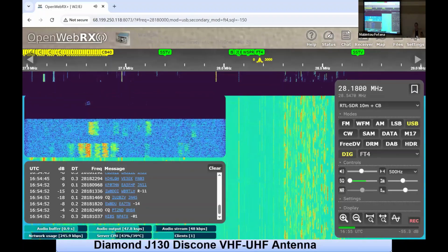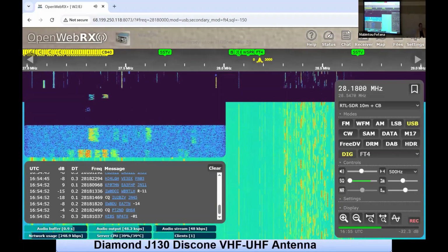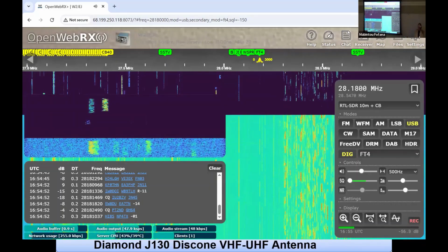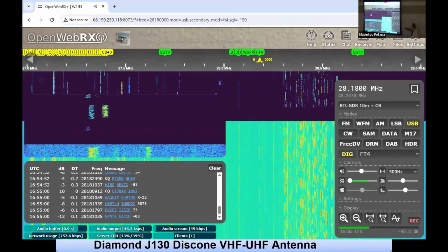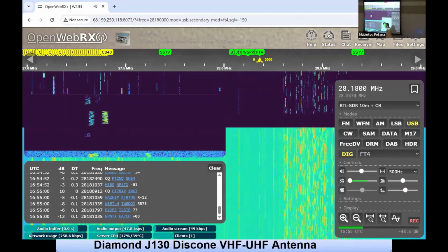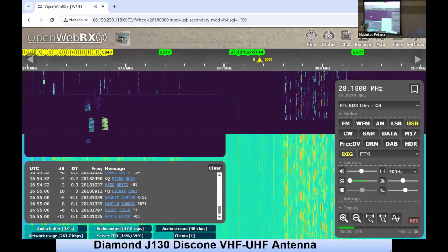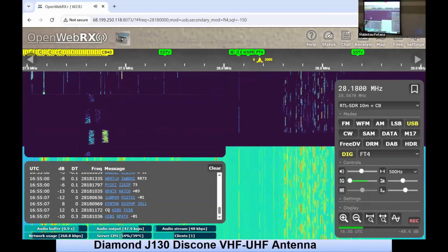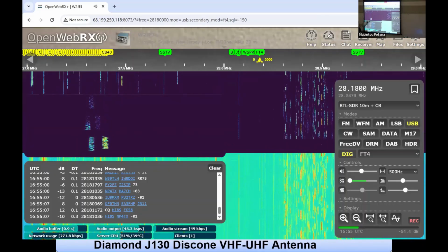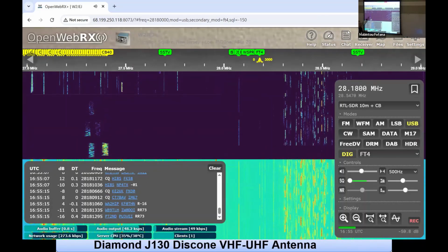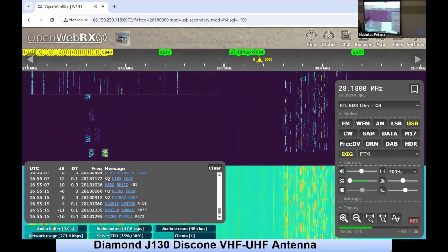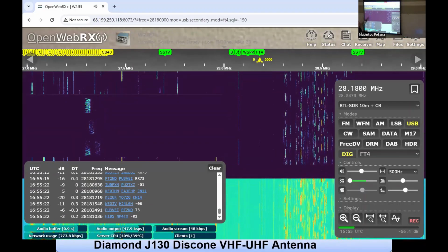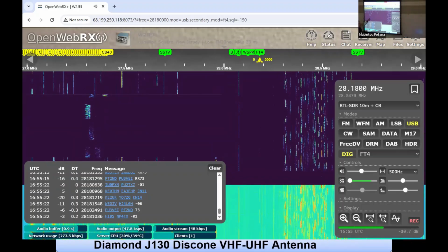I'm really looking at it from my perspective in Hamilton Square, with the antenna that's on my roof. These are the signals you're seeing. Now you notice the top is the broader spectrum. And then you have a small 200 Hz window where you're seeing the individual signals. Some of these are hardly seen. We work slightly below the noise floor, at the thermal noise floor.